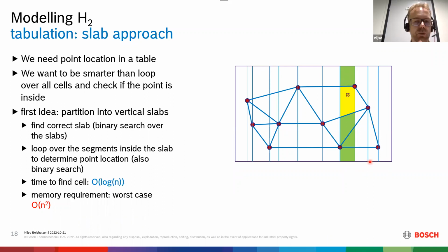Now, a couple of words about the lookup table. When you have an equidistant table, a lookup is very easy, but large tables are necessary. With unstructured tables, you can have local mesh refinements to accurately capture local extrema. So we need some efficient methods to find out in which cell in the table our query point is.